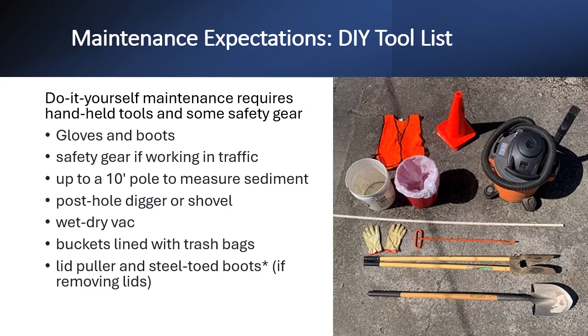A lid puller for removing a catch basin or drywell lids, and steel-toe boots to protect your feet in case of dropping a lid. However, given drywell lids can be very heavy and difficult to properly put back in place or retrieve if dropped in the structure, you might want to opt for a contractor to handle these structures.